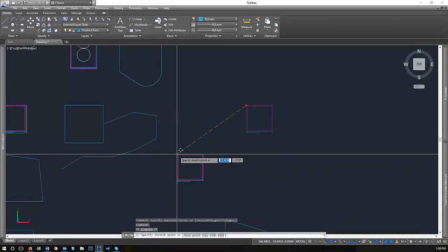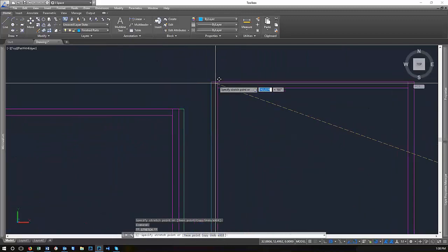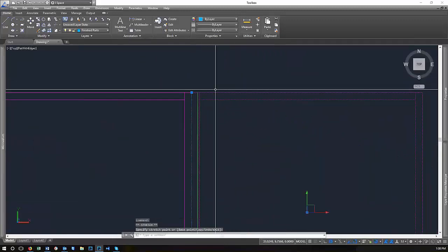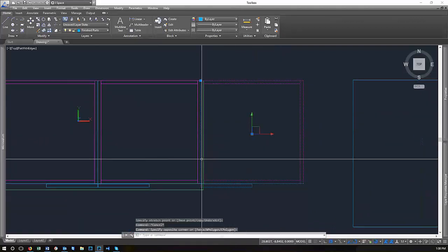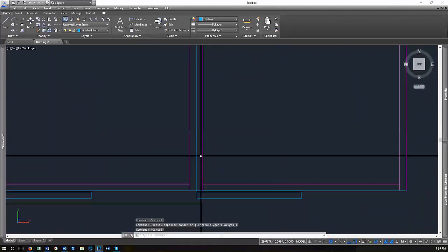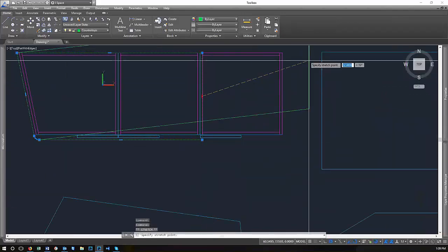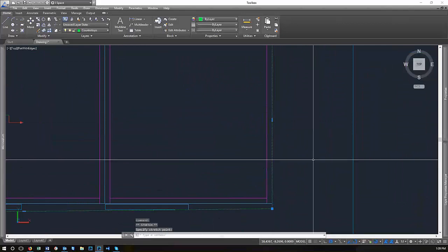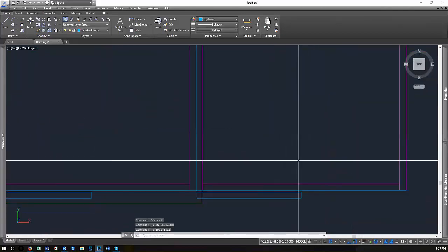So you've got a block, and you can place this block anywhere you want. So I perhaps want to add another cabinet here. Done. And now I don't have to worry about that stuff all moving around. Then I can click on this elevation, this countertop drawing, drag it out to here. Then I can even do a stretch command. Oops, I got that wrong. Let me undo.